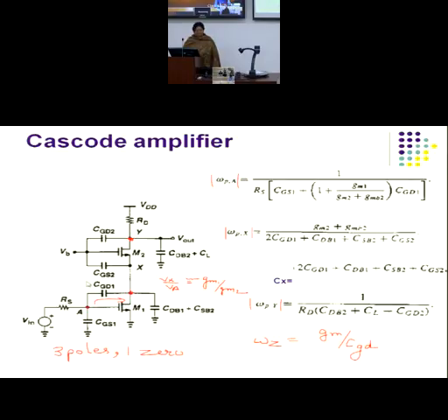I apply my Miller's theorem, separate it into 2 parts and find the pole at A and find the pole at X. Okay, and the gain that I should take should be Vx upon Va, because it is this gain which will come into picture. So it should be Vx upon Va. And then move from X to Y, identify if there are any further Miller components, but there are not, because this is not coming.